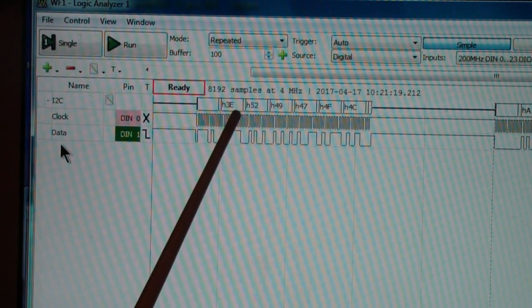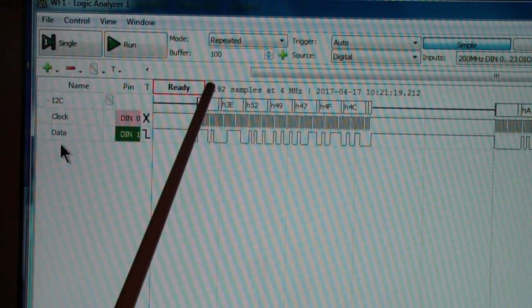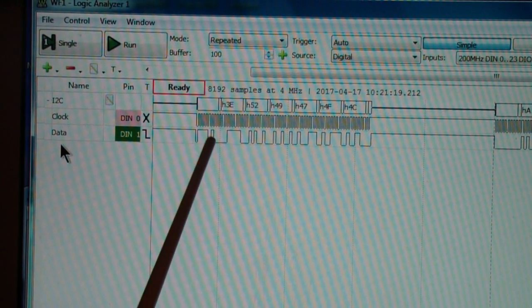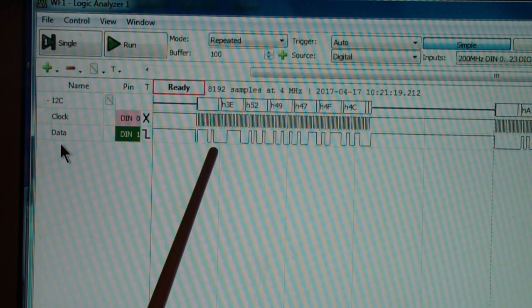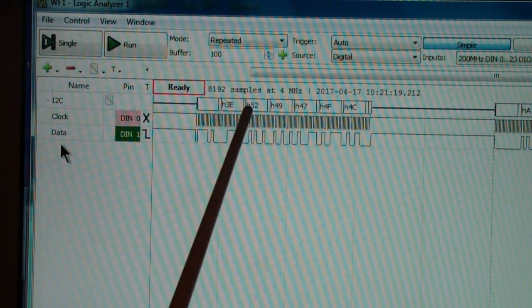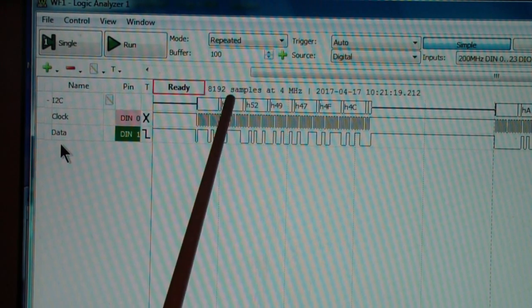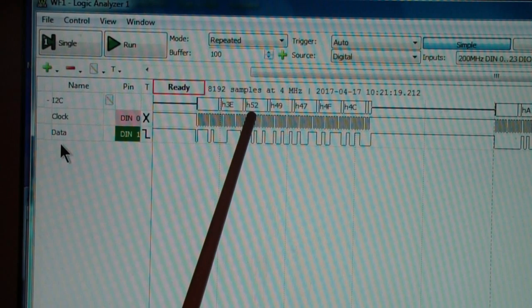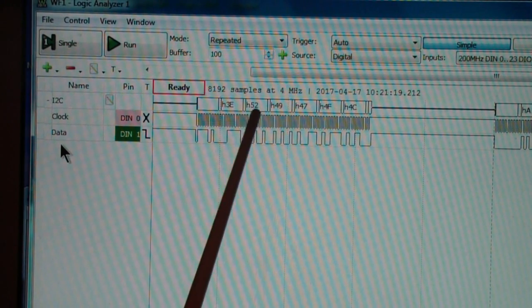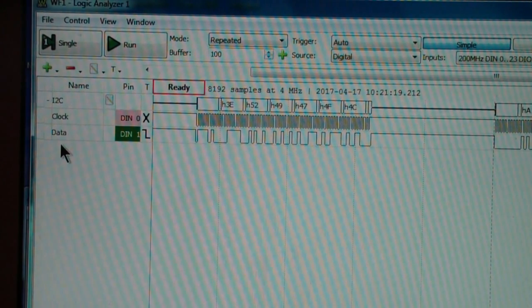bus output. The first symbol is basically just the command to start receiving the data. The only thing that changes from one to the next on this simulator, that is the Rigol demo board, is this first byte. After that, it just spells out the letters Rigol, R-I-G-O-L, in ASCII. Now, these are hex, but in ASCII, that would spell Rigol.